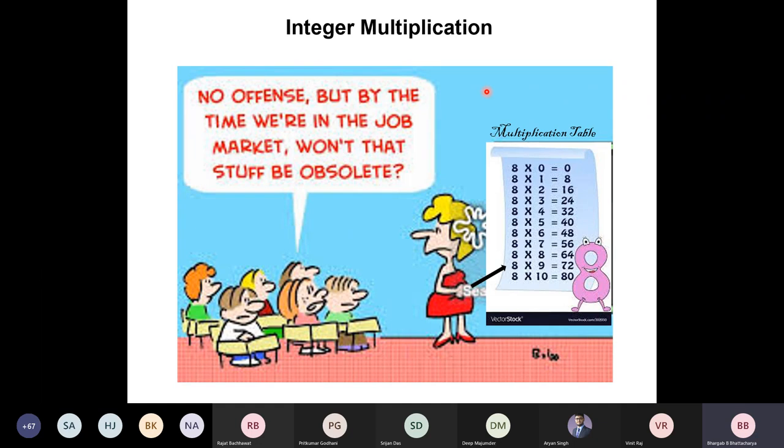Then we thought about improving the cost of the architecture. One of them was to consider a hybrid structure, combining ripple carry and carry look ahead together in different forms. Then we talked about carry look ahead architecture in multiple levels, which gives rise to the carry look ahead tree.